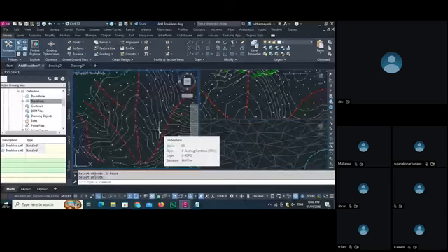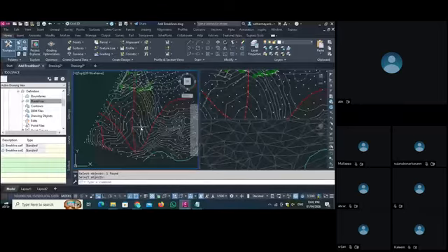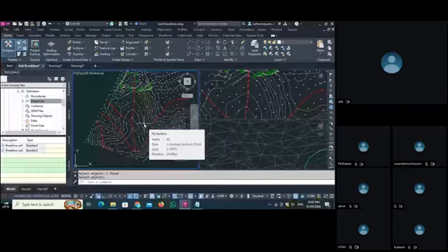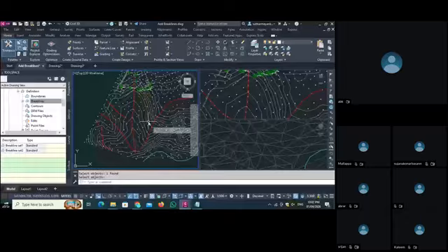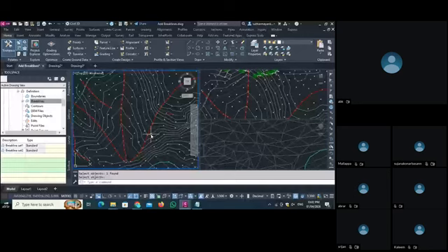When there is a project and they want to give a water slope as per their direction, for doing that work they insert one polyline, make it a feature line, or if they use a polyline, it is not an issue. They give the slope to that polyline after knowing the surface, and then they put that polyline into the surface with the help of this break line. As they put the line here, our contour is automatically connected with this.